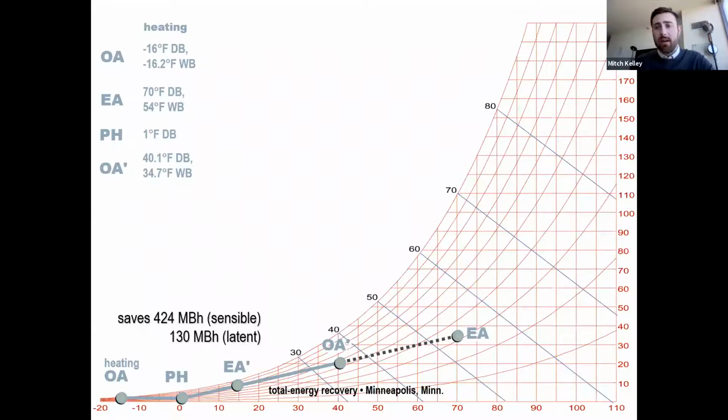So often the energy balance dictates that OA preheat will actually save you energy, even though you're dumping energy into that, because you allow the wheel to operate for a lot more hours of the year. But not a lot of designs have it. It's very interesting.